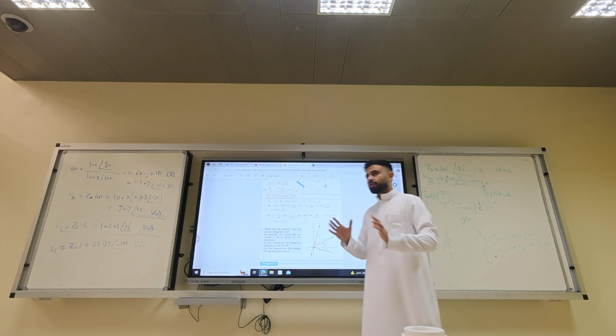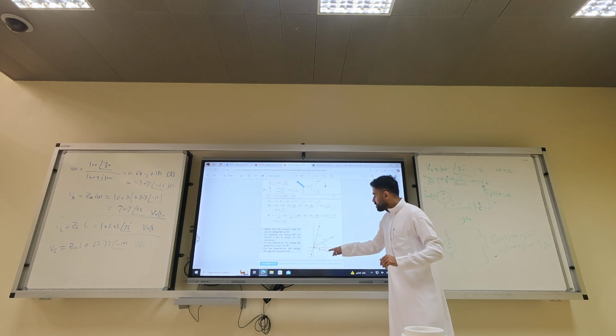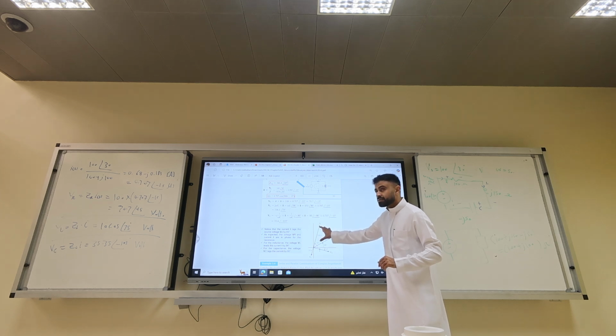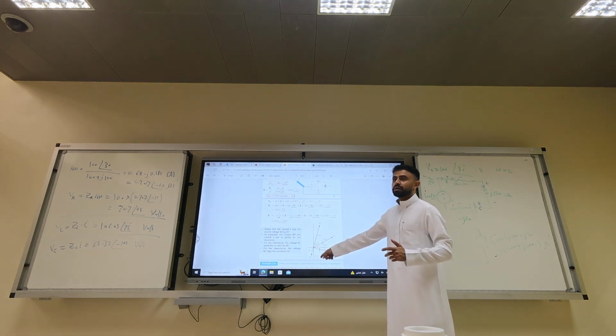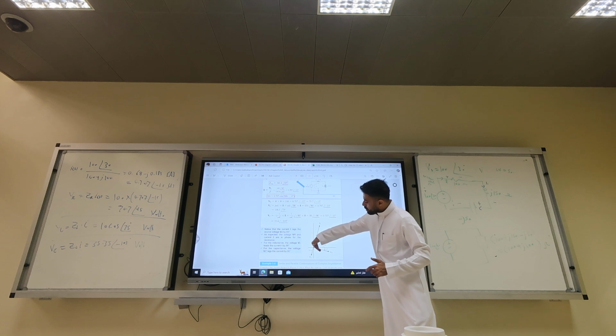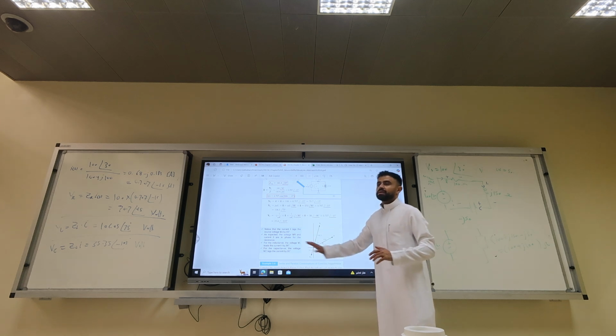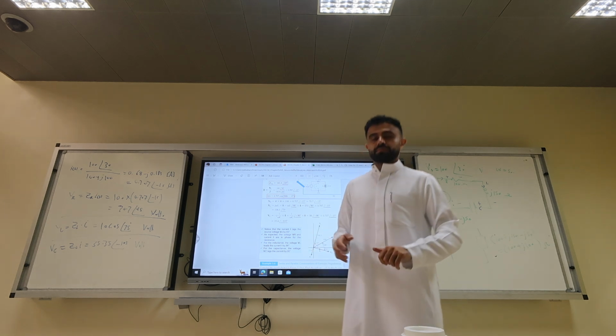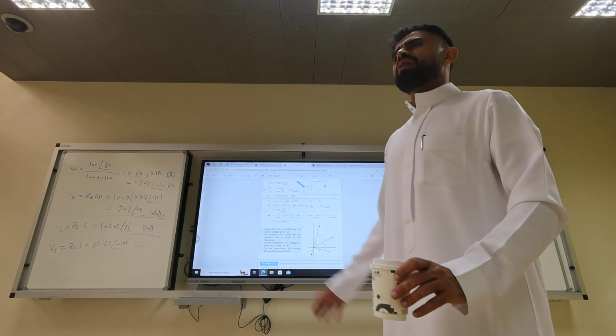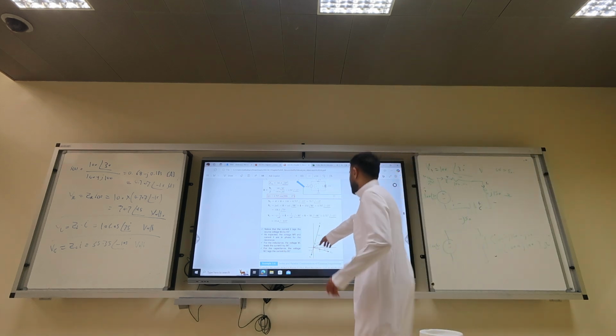But when you say leading or lagging, you have to look, for example, at the voltage of the resistor and the current of the resistor: they are in phase. For an inductor, the voltage would lead IL. IL is not plotted. For the capacitor, IC will be somewhere here, but it's not plotted. They all have the same current.